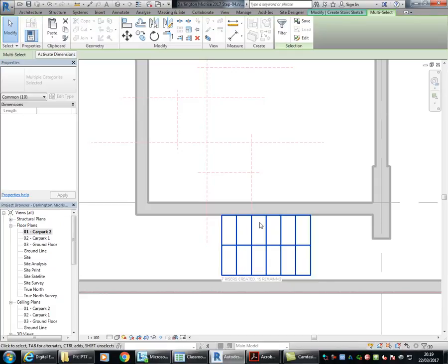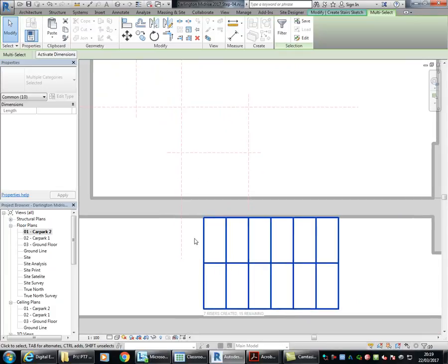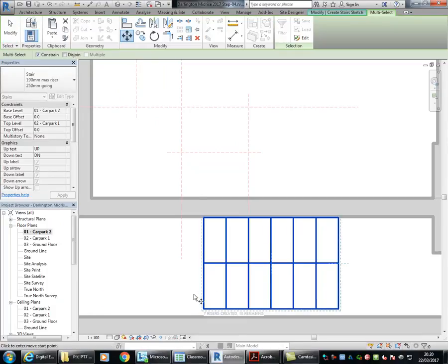And it still creates a 3D stair either way. So it's much easier making it with lines, I think. So again, I've drawn these lines, selected them, and now if I click the move button, I can snap it from the corner here onto the corner on my reference planes. But do you know why it's not moving diagonally?